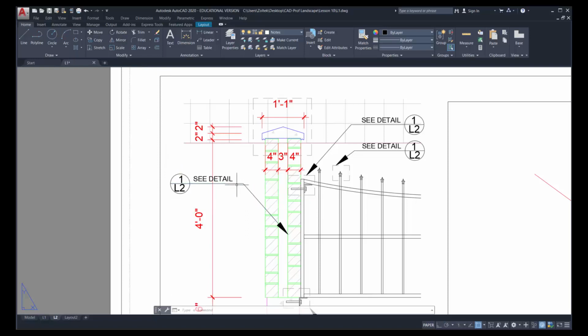Because I filleted it and they were two polylines, it simply joined them to become one. I can, like we did before, explode that line so it becomes two separate units like that. And that will then separate them, and we're back to where we were before. Now I'm going to rotate this line and that arrowhead from this position, the base of it, rotate it around till it's going to point at the corner of the box.